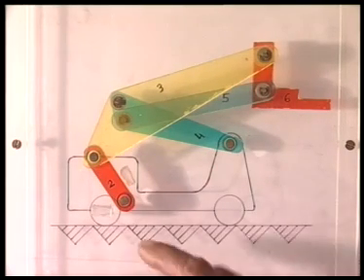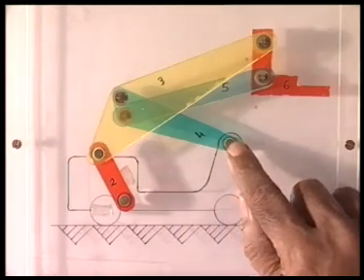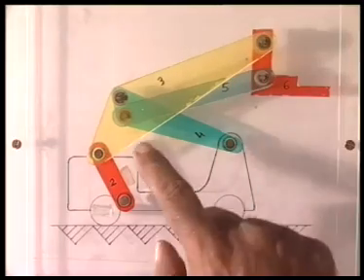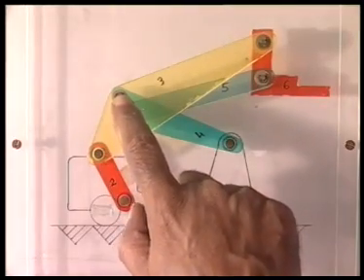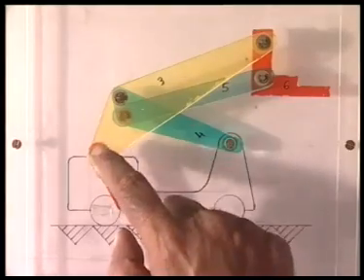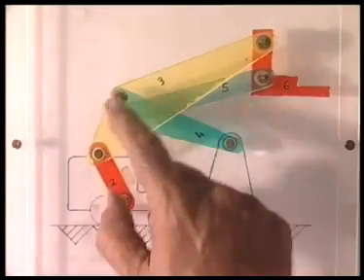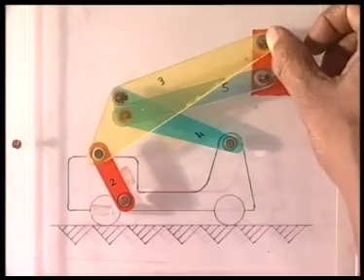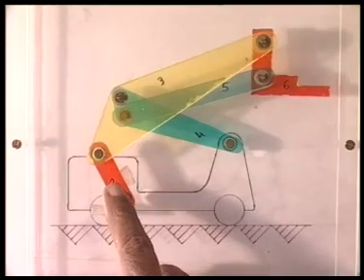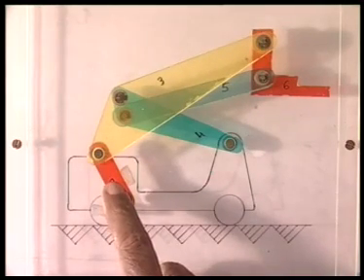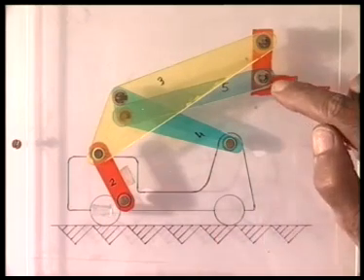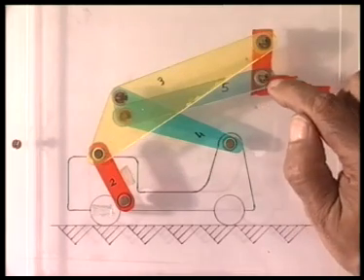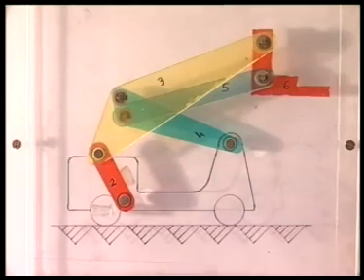Next, we chose O4 conveniently on the body of the truck. Then removed the slider and got a coupler point here at C such that O2, A, C, O4, this 4R link has a coupler point B which has an approximate straight line path, and the movement along that straight line path is coordinated with the motion of the input crank. In the third stage, we had chosen this point D again conveniently on the body of the fork such that a second point is guided along the same vertical path.